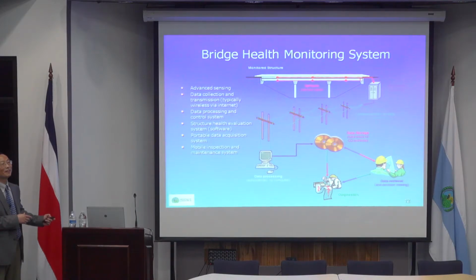They say, well, let's do a model. So they build a similar situation of the river condition. They put buildings in a similar situation, put it in a wind tunnel, and use the wind tunnel to test how these structures behave, and use that data to design. And everything else is the same. Because the AASHTO design code is only for short and medium span bridges. For long span bridges, it does not cover. So each agency will define its own design criteria.